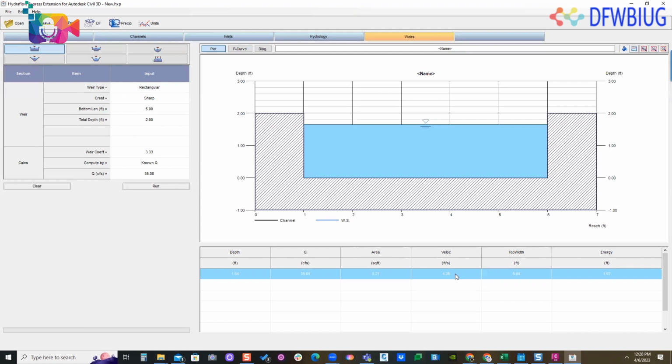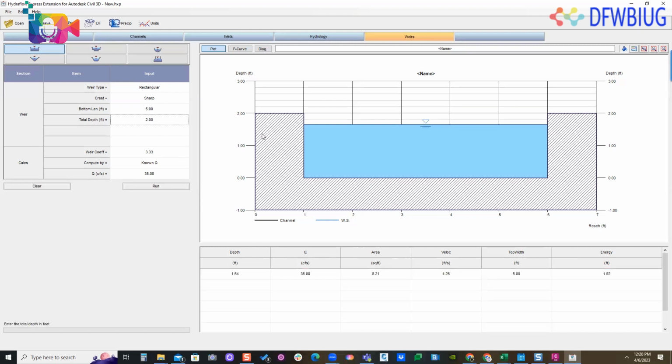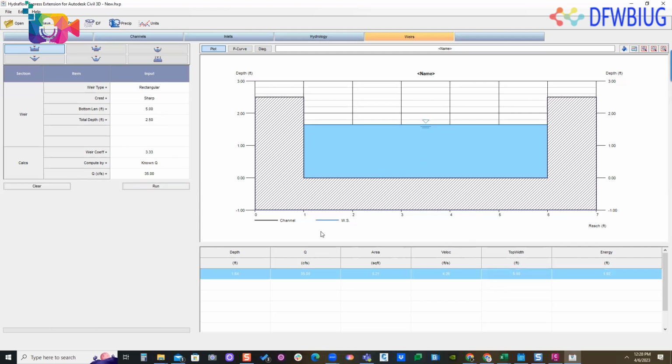You may put some riprap. I would recommend putting the riprap at the end, because most of these, like I said, wants only 2 foot per second being released. But here, this may work. I can probably, it's getting close to the top. So maybe I'll do, not 5, but I might do like 2.5 for the raise up my weir here. So I use this to do a simple calculation for weir calculations of release, the release from a detention pond.